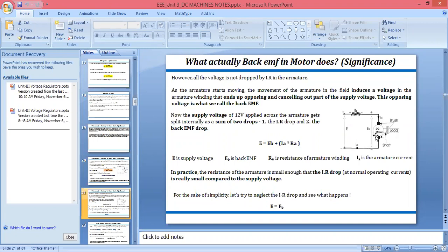So accordingly, KVL means Kirchhoff voltage law. Kirchhoff voltage law states that the algebraic summation of the potential drops or voltages for a closed loop will be zero. If there is a supply voltage, a battery, then the summation of the voltages for this loop will be zero, and you take the direction according to the sign convention.